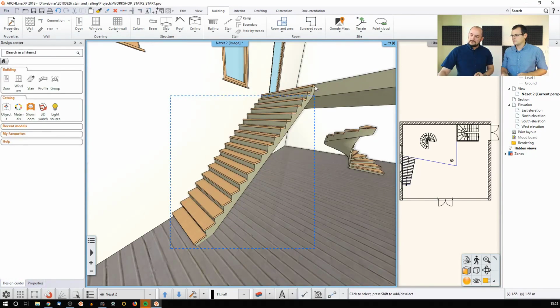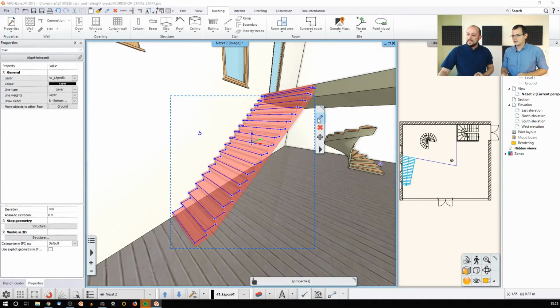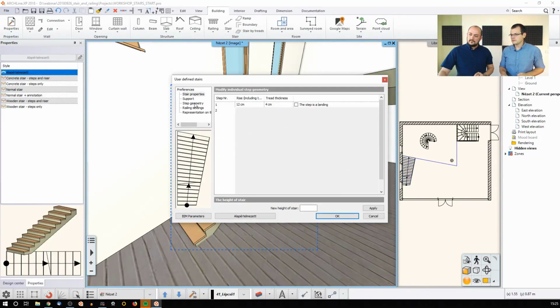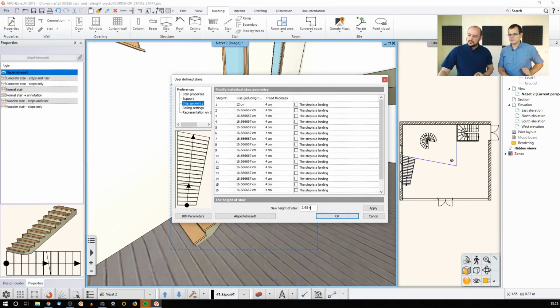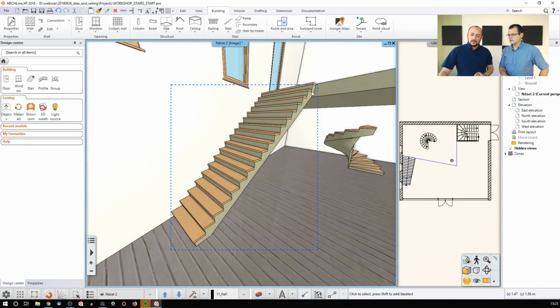See, there is this little gap, that 4 centimeters that is missing. But if I go back and change it again and find this option, let's just go back and change it to 3 again, apply evenly distributed, and OK, and now it reaches the perfect height. I see. So even though you are working based on exact lines, you can still fine-tune it in some way. Yeah, and anytime, step by step, or also evenly distributed again.